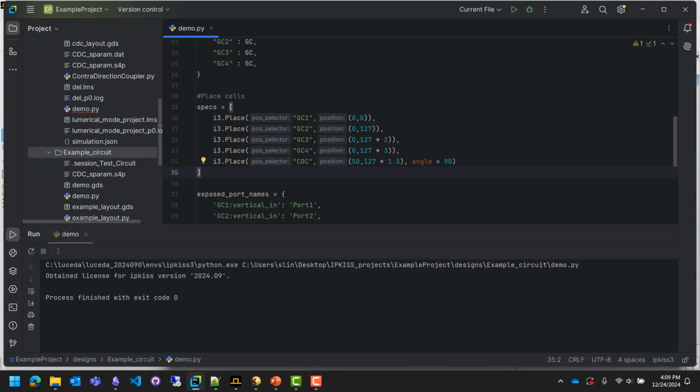So next, what we can do is we can try to route in some waveguides in the next section, and then we'll connect them to the grating couplers and the device, and then we can build our circuit out and create a transmission response from the S parameters.